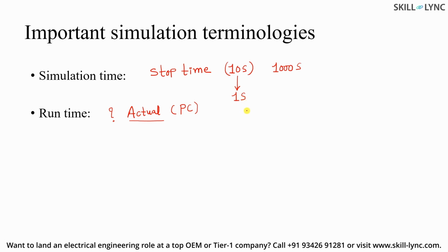Let's go to the next terminology, which is sample time or time step. This is a very important terminology. A sample time or time step is nothing but the time duration, or a piece of time, for which the model is solved on each time step.